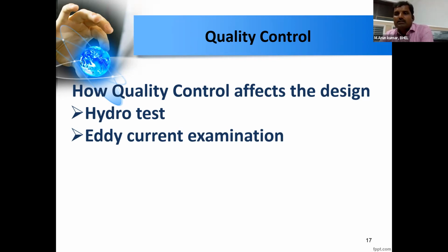When we do boroscopic examination or when we cut the sample, we could not identify any defect or any variation in the surface at that particular location. So what we found was that the change in impedance, change in current, everything gives some spurious indications in the eddy current examinations. So we have done a lot of research and we found out that some of the indications do not form a proper loop, or are harmless for the design.